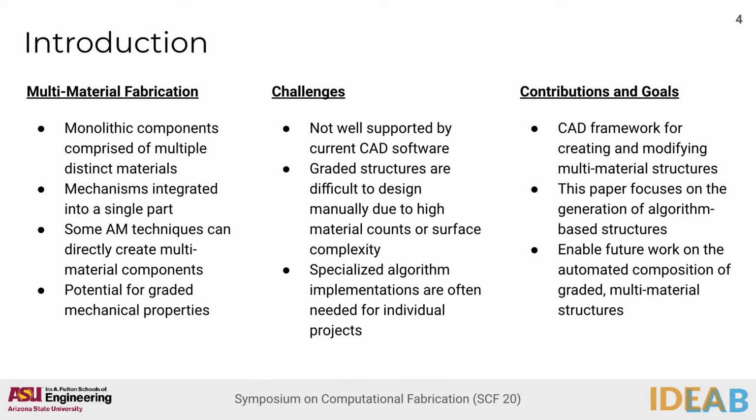We focus on three structures in particular: a lattice structure, a triply periodic surface, and a dithered structure, all of which have applications in graded materials. This work also enables future work on the automated composition of graded multi-material structures by providing a single tool integrating multi-material design, simulation, and process planning, by enabling automatic processing of classes of parts, and by reducing the need for developing specialized algorithm implementations for individual projects.